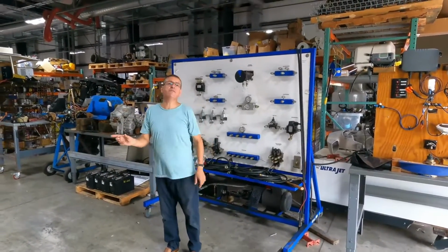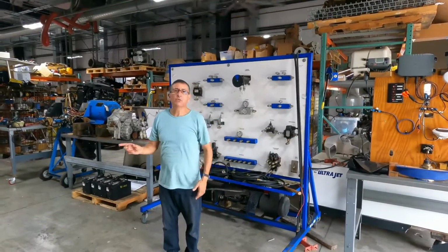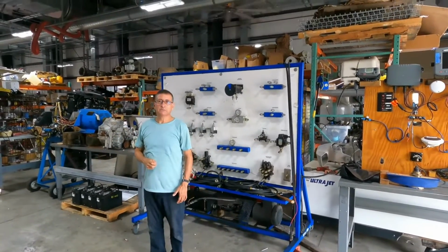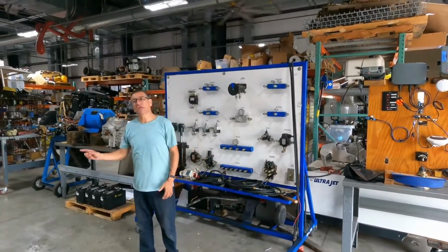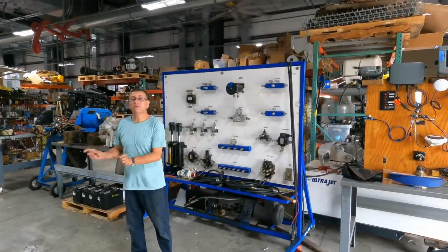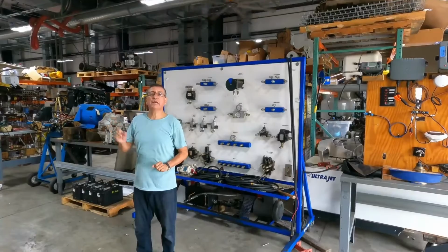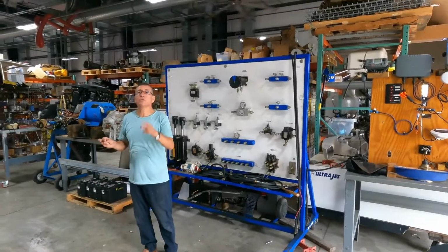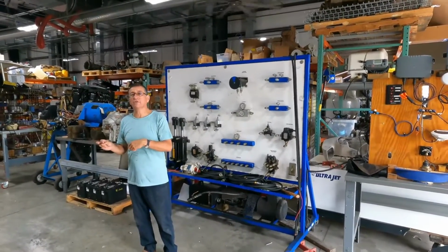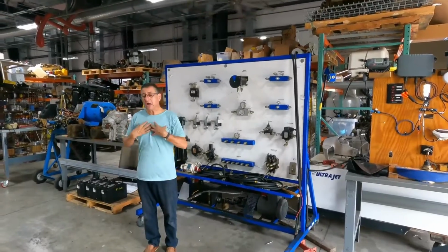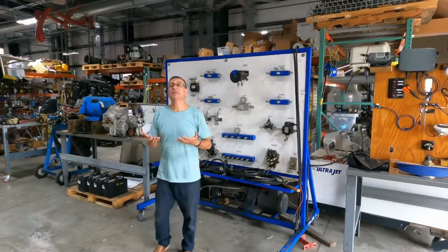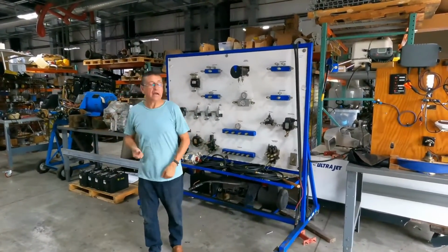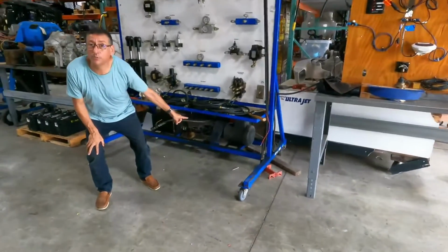At the bottom, I have the total flow that I need is 20 gallons. And the total pressure is 450 psi. That's okay? This is the total flow, and this is the total pressure. With that pressure and that flow, divided by the constant, I calculate the horsepower. With the mechanical horsepower, I convert to electrical with the formula 1 horsepower equivalent to 746 watts, and I calculate the motor. And now I have the motor and I have the pump. I need a pump of 20 gallons with a pressure of 250 psi, and I need an electric motor of a minimum 2.2 kilowatts.